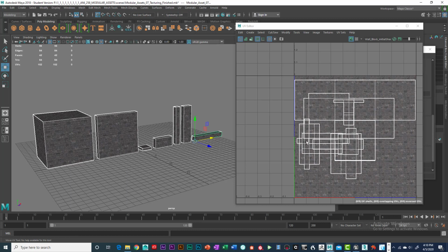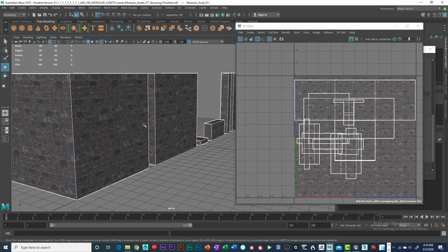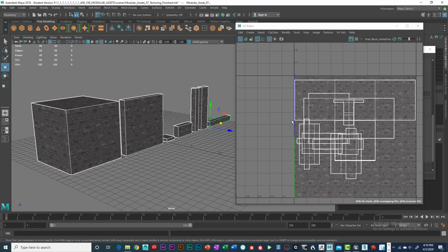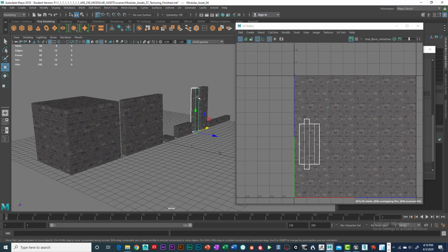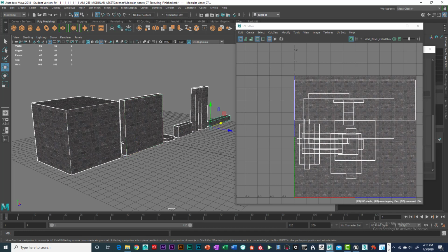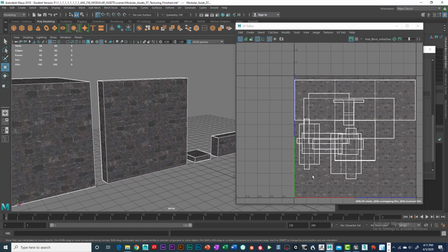I'm not really interested because I'm only sharing 1 UV, and I'm actually using just one texture map, 4096, for all 7 pieces. So I think I'm using that texture space very efficiently. Even though there are those overlaying issues, I'm not too worried because they're separate objects. It doesn't matter. If it was one object and it was sharing UV, you can't overlap. But several different types of objects that are separated, absolutely. You can overlay them all you want as long as you don't have a problem with the texture.